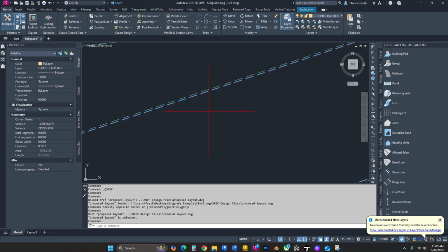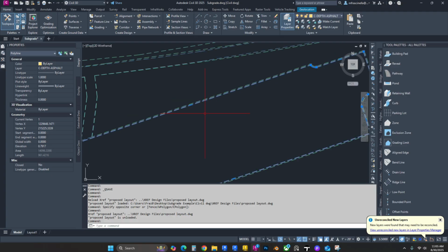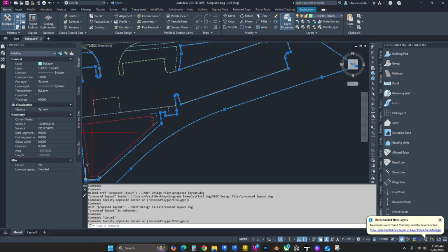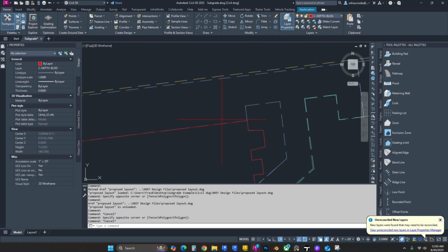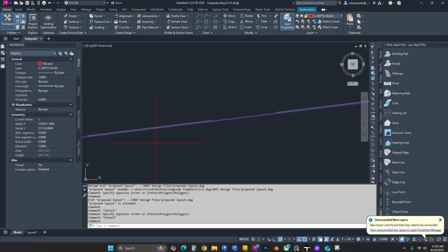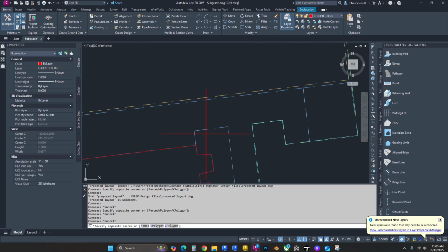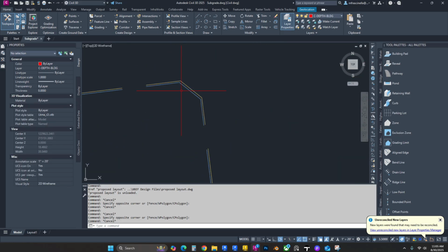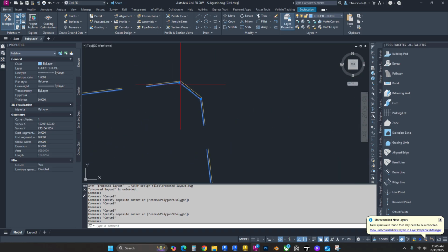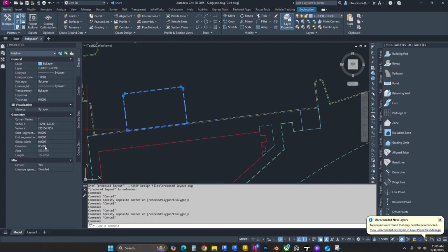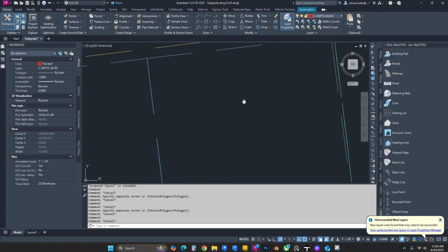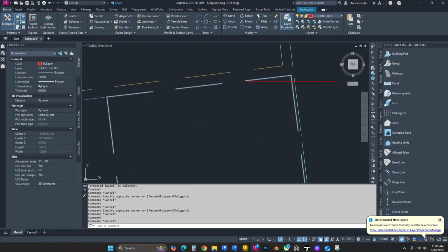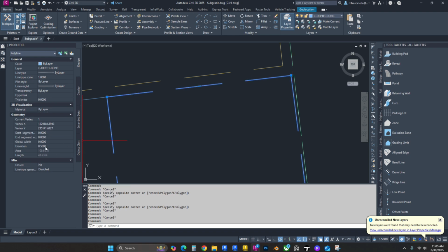Well, 3 inches of asphalt, 6 inches of RCA. The topsoil and seed areas, we have at 4 inches thickness. The building, we have at a foot of thickness. We have 4-inch concrete sidewalks. The concrete ADA stalls are going to be 6 inches thick, so 0.5 elevation. And then we also have a dumpster pad over here that's also going to be a 6-inch concrete slab, which is 0.5 for the elevation.